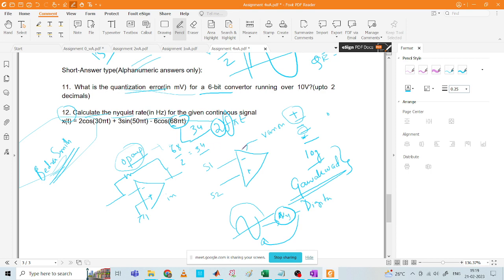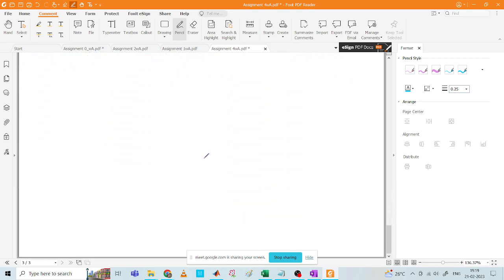But you tell me one thing, I'll give you a very easy problem. Let's say you have a sine wave. The frequency of this sine wave is 100 hertz. So what should be the Nyquist sampling rate? Greater than 200. Very well. Is it greater than or equal to, or greater than? Greater than or equal to, sir. Okay, so I can sample at 200, right?